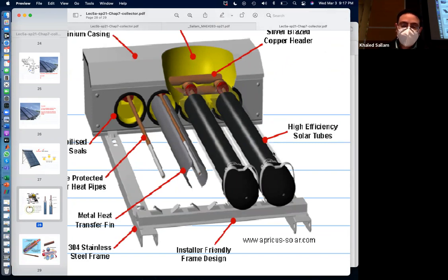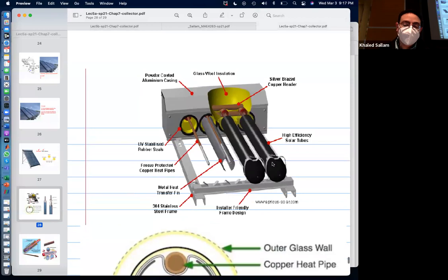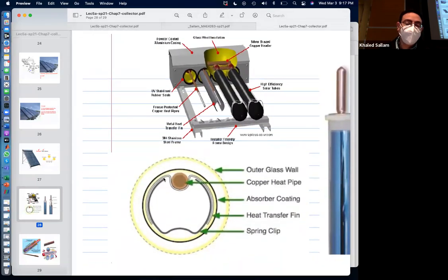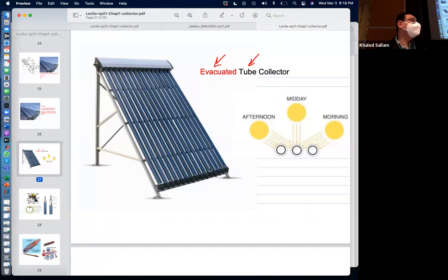See how the black collector is a cylinder, and the tube is stuck to it, soldered to it. And this black collector is sitting in a glass tube, and everything here is under vacuum. So no conduction can go from that guy. Everything is just radiation. And if I do a good job selecting the coating, and my emissivity is 0.06 or something, then that guy will get heated and will not really radiate back. And it's not conducting back because it's sitting in vacuum. So you will just arrest the heat. So this design will allow you to function even if you are in Alberta, Canada. Doesn't matter how cold you are, this guy will take the radiation and hold on to it, and it's not going to go away.